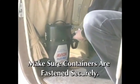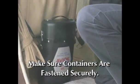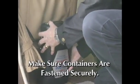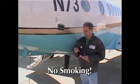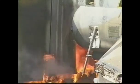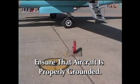Inspect your portable oxygen storage containers to make sure that they are securely fastened in the aircraft. Turbulence or abrupt changes in aircraft attitude can cause them to come loose. Do not allow anyone to smoke around oxygen equipment that is being used or when maintenance is being performed. Oxygen supports and rapidly accelerates the combustion of all flammable material. Ensure that the aircraft is properly grounded before loading oxygen.